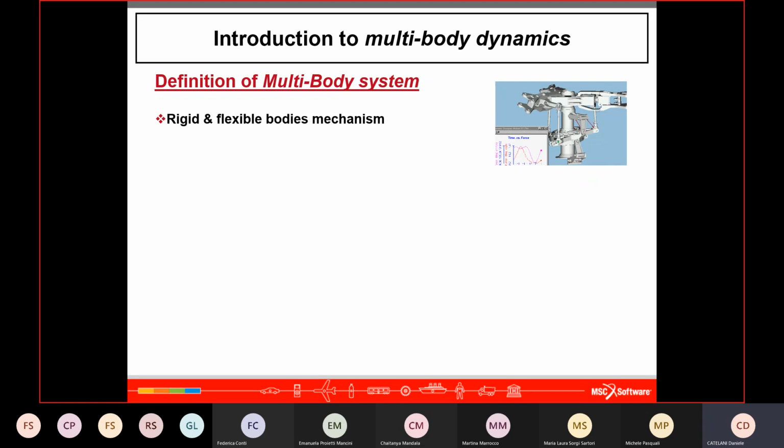When you are in an advanced stage of your design, for sure, you can replace the preliminary geometric representation with advanced geometric representation, importing data from a 3D modeler like CATIA, Unigraphics, PTC, SolidWorks, or other tools like this. When you use flexible bodies, you need to have a good geometric representation because the structural results depend on the shape of the body.